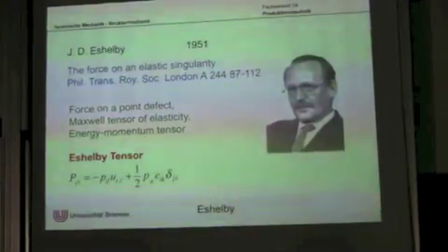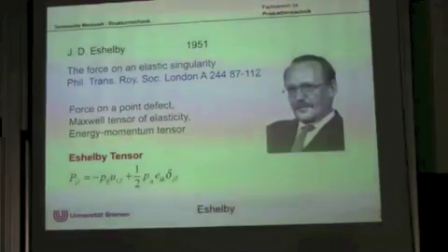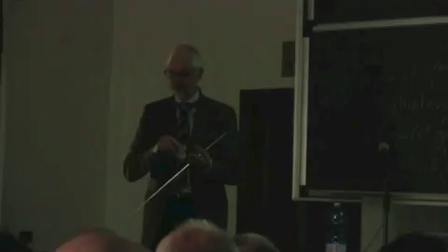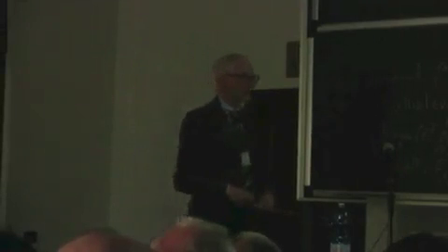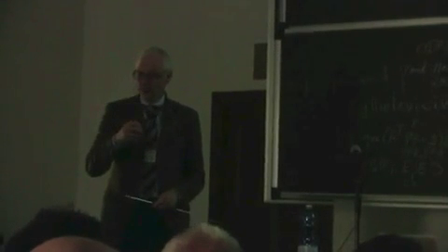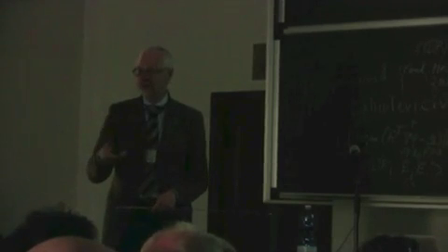And this can be interpreted in the following way. If you have in a body some singularity, for example a crack tip, or a dislocation, and this dislocation is displaced a little bit by changing the configuration, then the energy will change. And if you differentiate the energy with respect to the position of the defect, you get something that has the dimension of a force. And it is this material force that is called driving force in this way. If the defect can move within the material, it will move, because it can reduce energy.